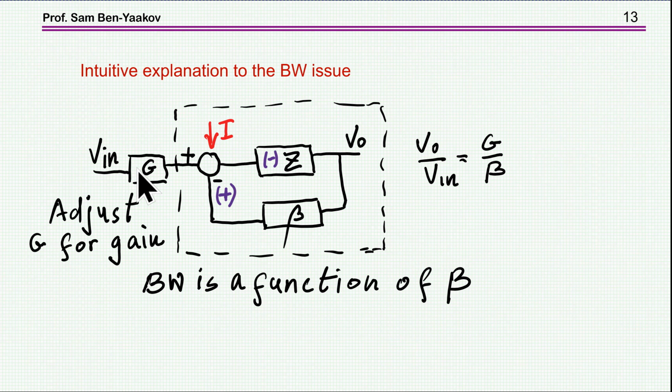And I'm showing it here that if the Z itself has a phase reversal, then the transfer function between input and output will be negative. If, however, the reversal is in the feedback and this has no phase reversal, then the gain will be positive.